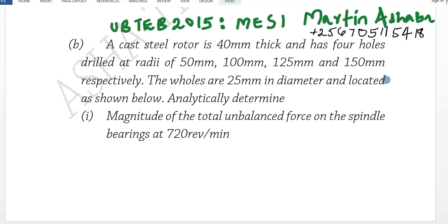Therefore, an engineer must work hard to ensure that unbalanced force is put out of action by either adding another mass to counterbalance that unbalanced mass, or by drilling a hole on a rotating machine component to counterbalance the effect of the other inertial or centrifugal forces that are bringing an unbalance in that machine component.